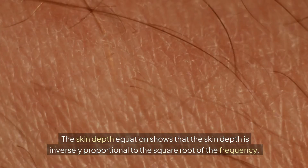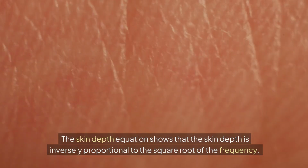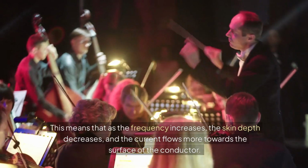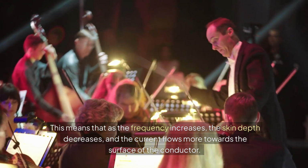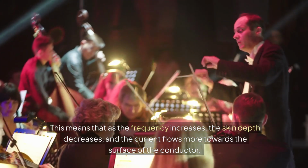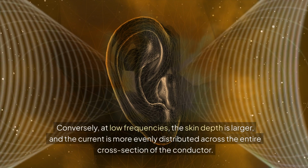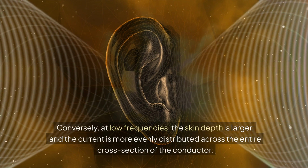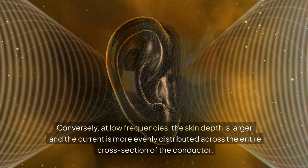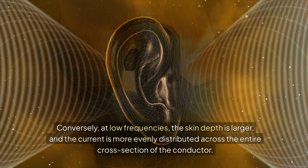The skin depth equation shows that the skin depth is inversely proportional to the square root of the frequency. This means that as the frequency increases, the skin depth decreases, and the current flows more towards the surface of the conductor. Conversely, at low frequencies, the skin depth is larger, and the current is more evenly distributed across the entire cross-section of the conductor.